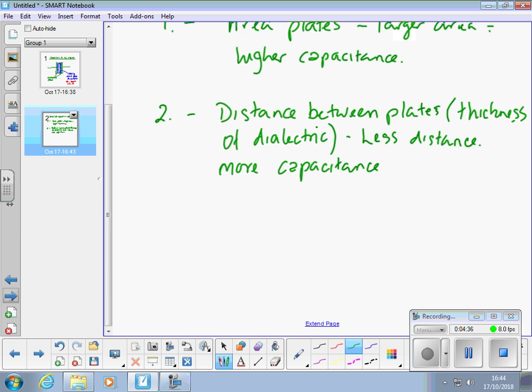And thirdly, it's inherent in the material used for the dielectric. I'm not an expert in capacitors and the different types, but certainly of the examples I put, air is the worst dielectric. You're talking about its dielectric strength and its ability to withstand charge leaking through it. Although you say it's an insulator, there isn't a perfect insulator out there.